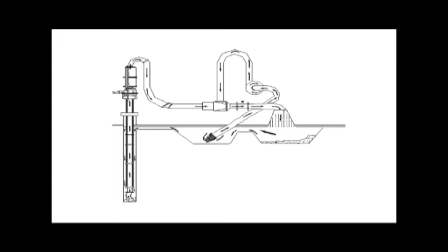Simple water is used, as a jet of water, to make the mud slurry and take the muck out of the pile cavity, and once it is done, the water is taken into the trench and allowed to stand still, so a proper steady state is given to the water there. After the water is still, the mud or silt particles settle down, and the water can be reused from the trench.